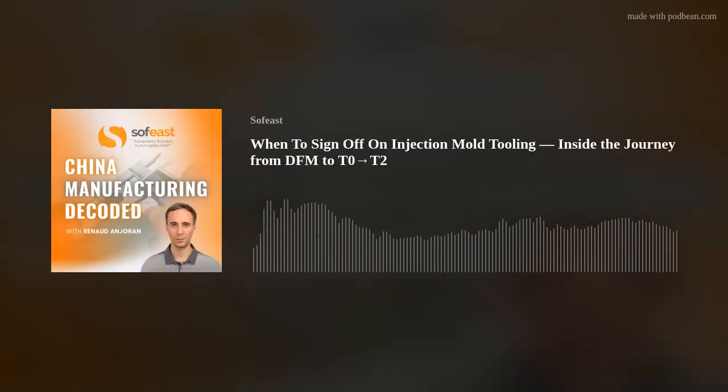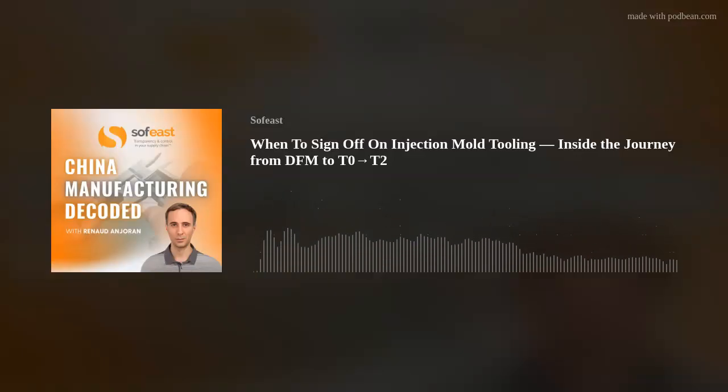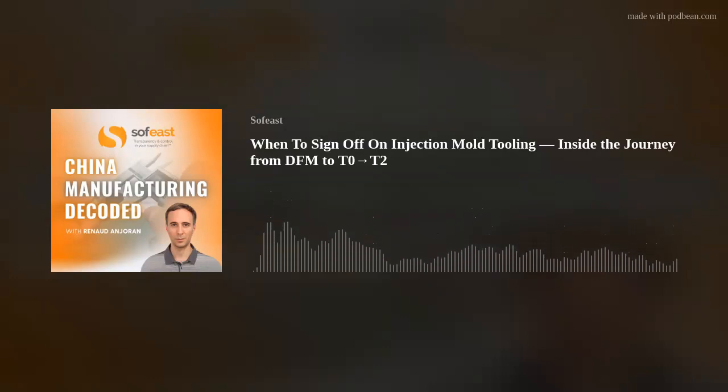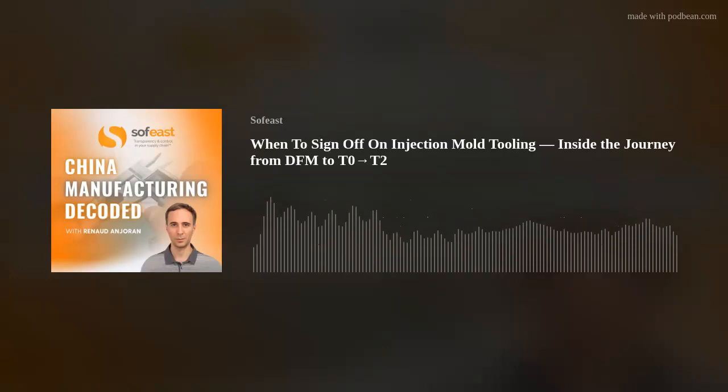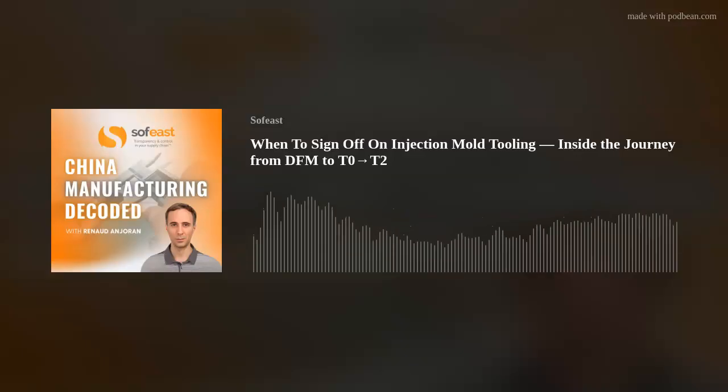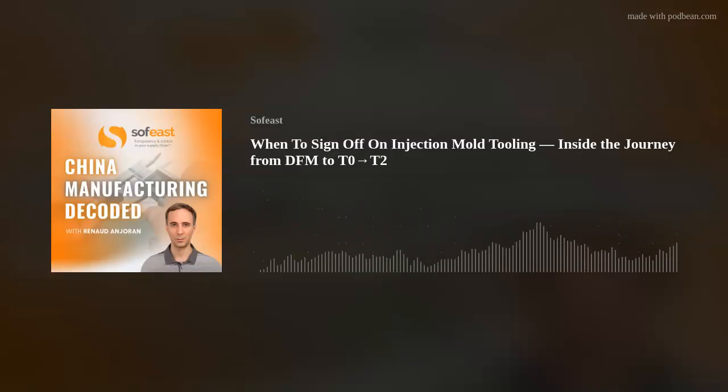If we need to customize, for example buy a custom hot runner that is only made in Germany and needs to be shipped from there, that's going to add 2 or 3 weeks to the procurement time itself. So where possible, stick with standard components in the procurement stage of getting all of the parts in for the injection mold tool.